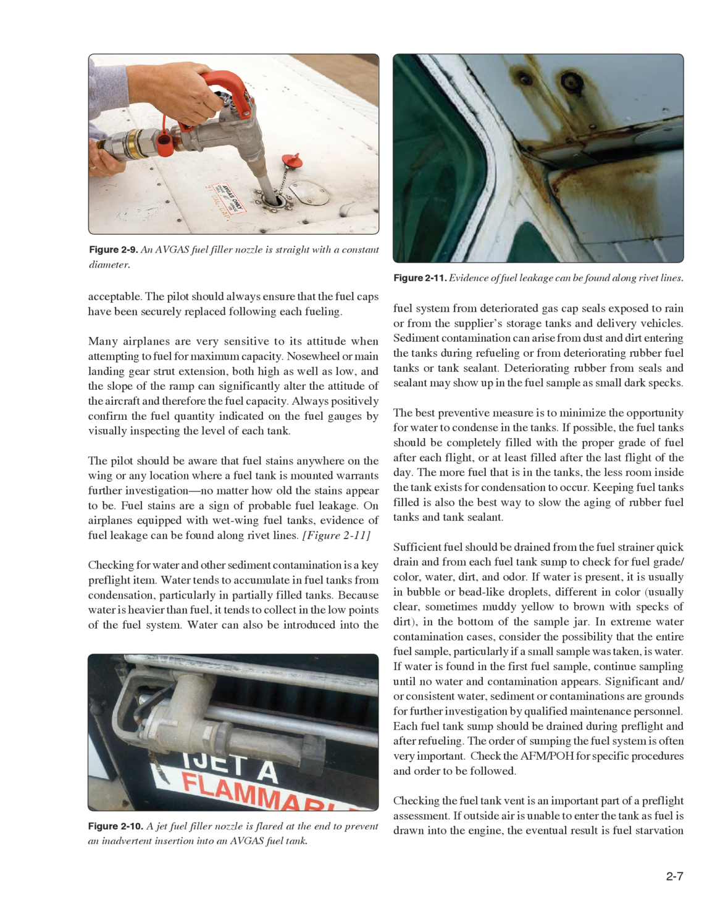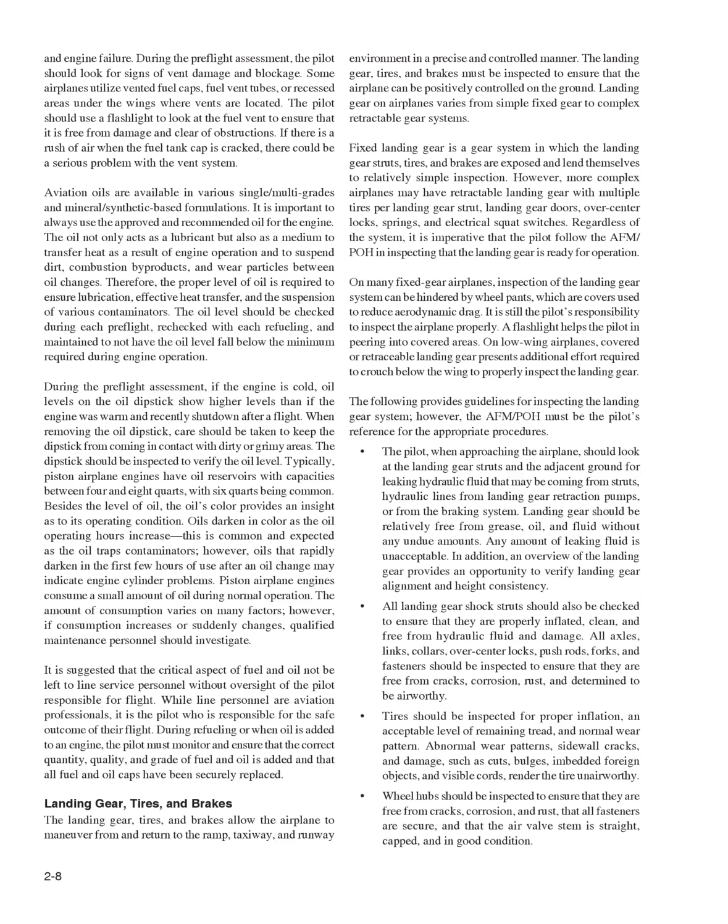Checking the fuel tank vent is an important part of a pre-flight assessment. If outside air is unable to enter the tank as fuel is drawn into the engine, the eventual result is fuel starvation and engine failure. During the pre-flight assessment, the pilot should look for signs of vent damage and blockage.